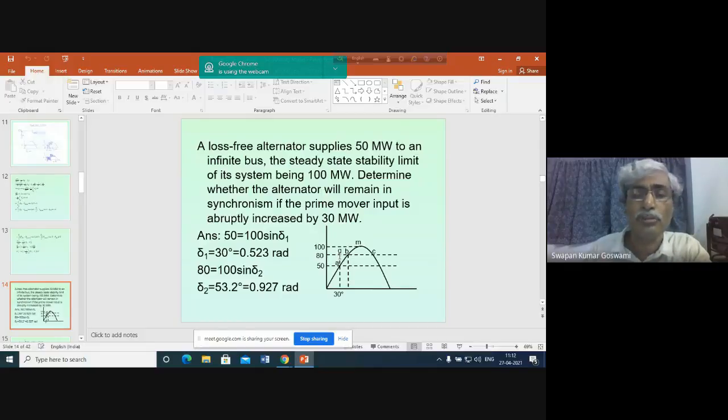To do this, what is required? You see that from delta 0, this is the initial operating angle. Now this becomes the new power input line. So obviously this triangular shape, this area, which is very similar to a triangle between A, G, B, A, will indicate the area where the energy will actually be imparted into the rotor.